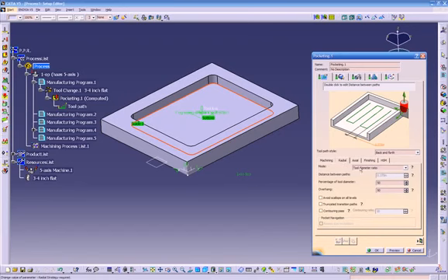Radial. It's asking us over here the tool diameter. So you just put over here kind of like a step over. So right now it's 50%. So the step over ratio is 50%. Or we can put distance. So right now we put step over 375. Step over from here to here, we get 375. Or we can put the step over ratio or maximum distance.